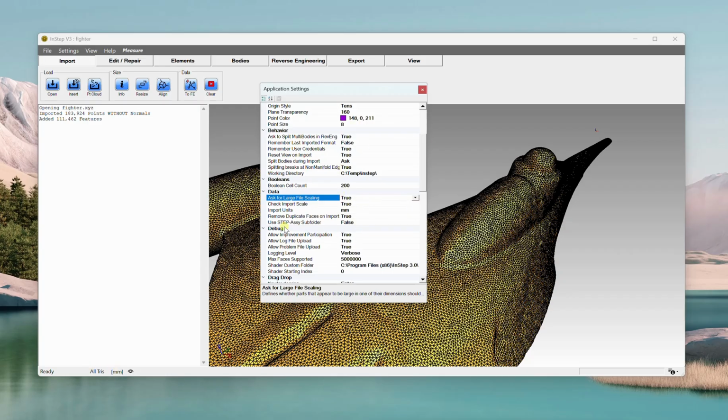The reason that's there is that in the past, people have been confused because they loaded data and it just showed up as a single point in their standard scaling. And the issue for that was that it was originally saved as, say, meters, and they were looking at it in millimeters. So there's a factor of 1,000 between. Things along those lines will generally need to be set.